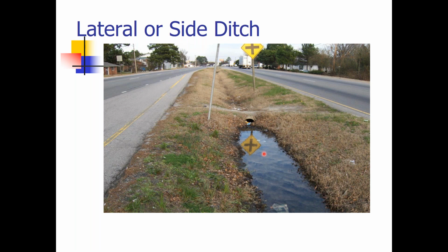But another note that was brought up, and I think is very valuable, is you see all the debris that is there. Even if the water were at the level of the pipe, that debris is going to block it. It's not going to cause the water to flow, and you'll notice it's not even going to the other side. Also, it's too high. The water's sitting there, and as best as I can tell, this is not a high quality area. This is not what we would consider a wetland. This is just water that's not drawing down quickly enough. We want to make sure when we put our pipes in, when we're doing our ditches, we're actually moving water along.